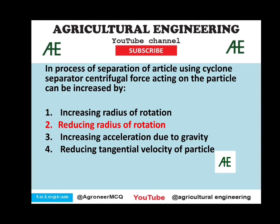In the process of separation of particles using a cyclone separator, centrifugal force acting on the particle can be increased by reducing the radius of rotation. There is a formula for centrifugal separation, for how much centrifugal force is needed.